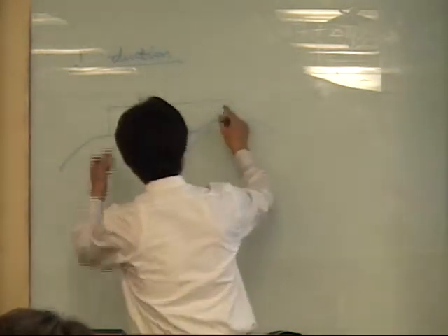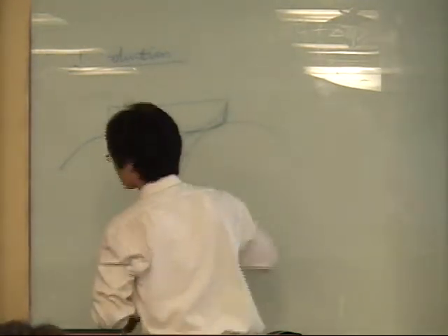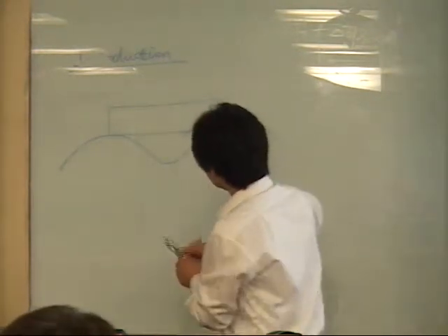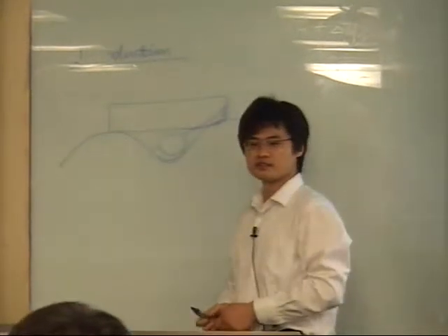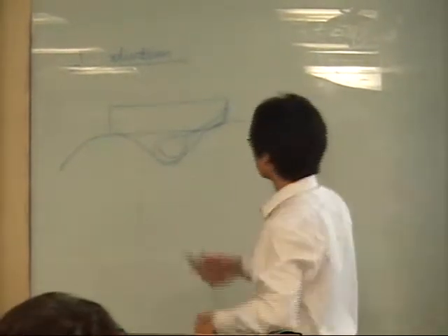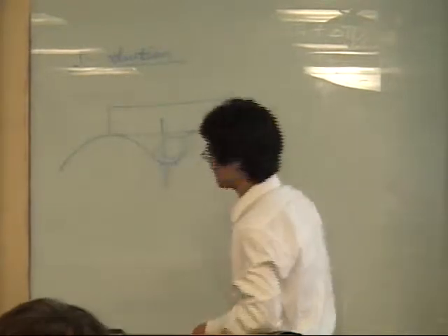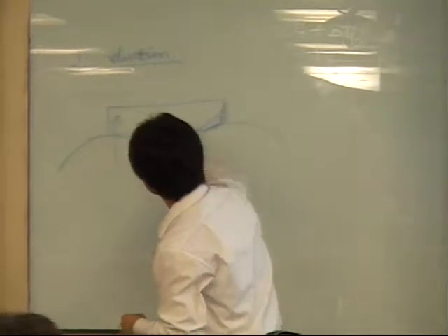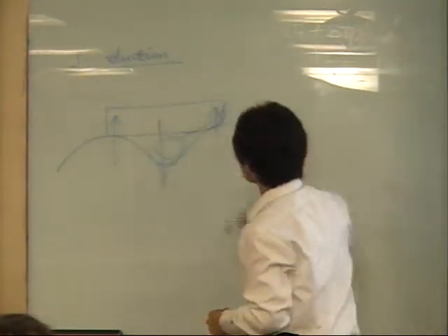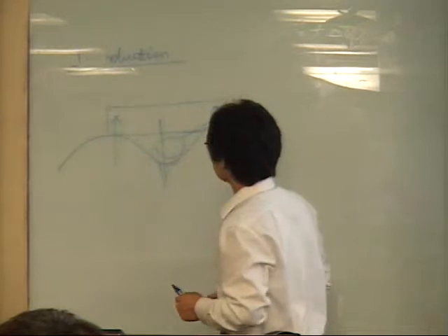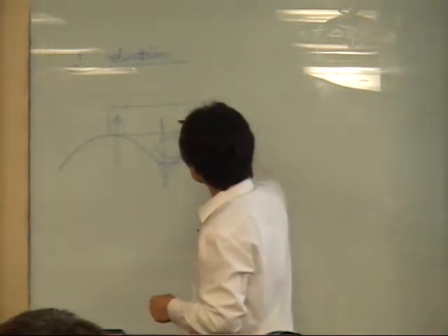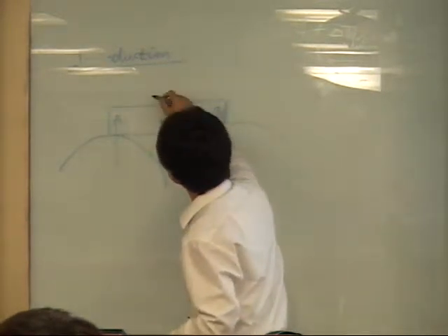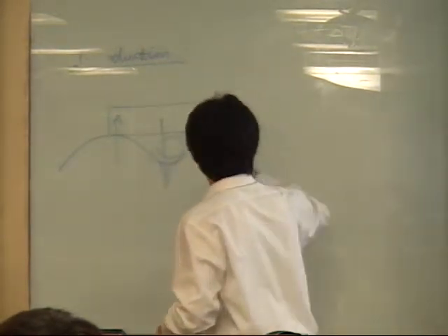When the length of the ship is approximately equal to the wavelength, this part is like suspended from the water, so it has a very large moment. The ship bends this way, due to gravity and due to the floating force, buoyancy, and it will introduce a very large moment in the middle section. This is called hogging.